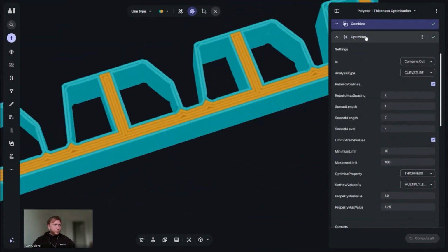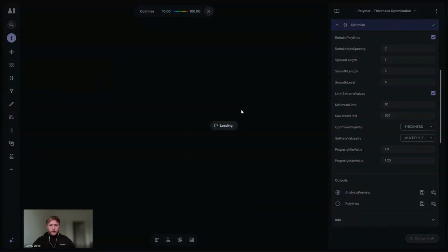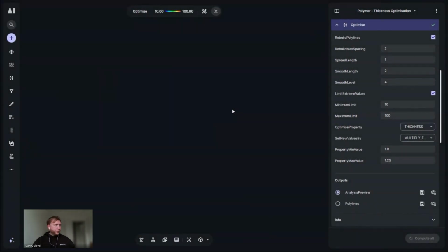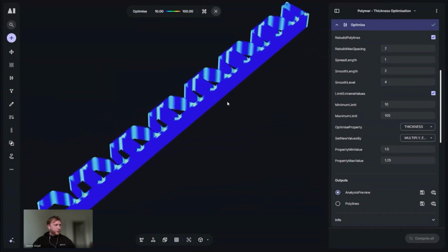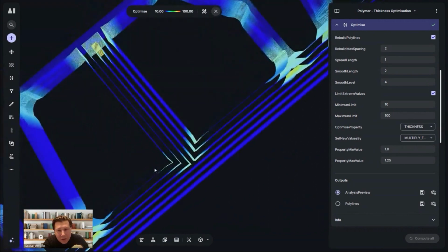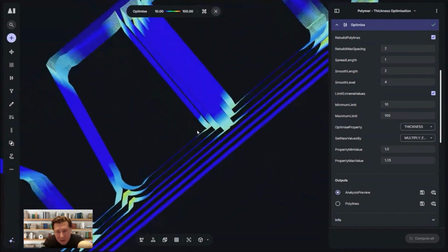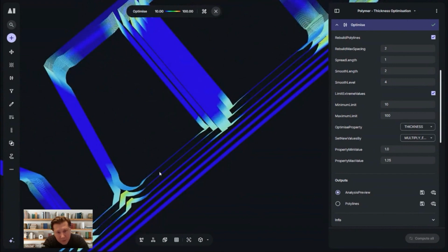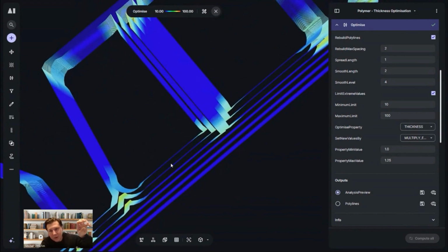We can use our optimize operator to analyze for curvature like we did before. You can see it will highlight all of the different corners of the part, and we can apply thickness multipliers here. But we want to be more targeted than this. Because in the corner, on the first move you did, it moved inwards. But with the optimize, you can bring that back, as you showed before, with the speed to the actual fillet. So still close the gap, but still retain the border. Yeah.